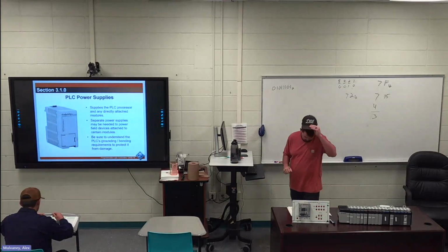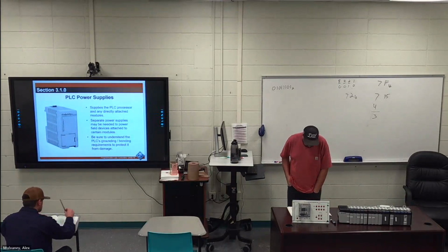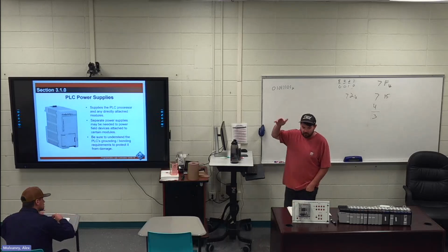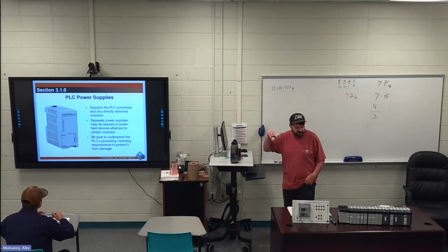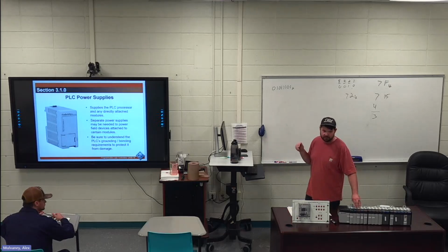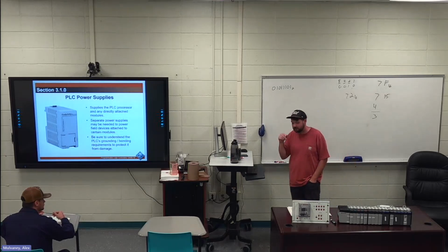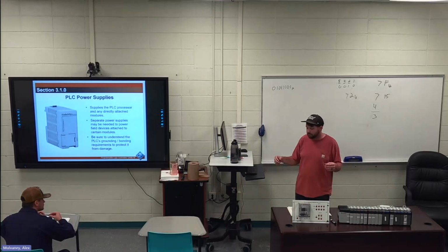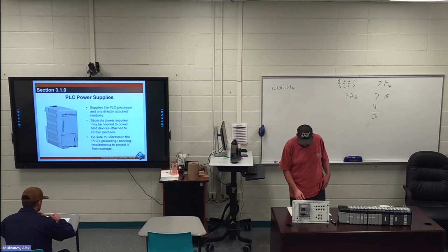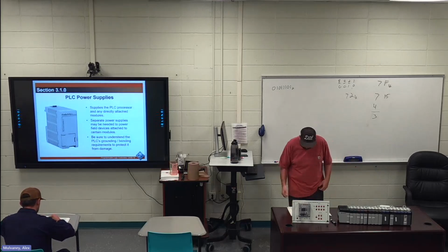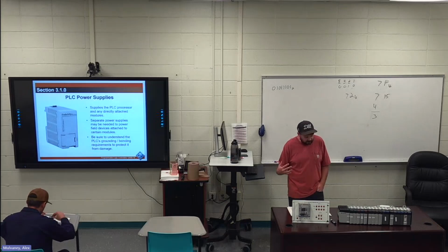Section 3, PLC hardware. Address. Whenever I was going through an HMI and you've got the analog thing that's going up and down, that address is what's tied to inputs and outputs. It's specific to the PLC brand. I talked about Allen Bradley and Siemens and GE all having different PLCs. That's where they get a little different, in how they do addresses. But you just have a unique number that is tied to each of those things. That's what addresses are. You need to know where it's going.